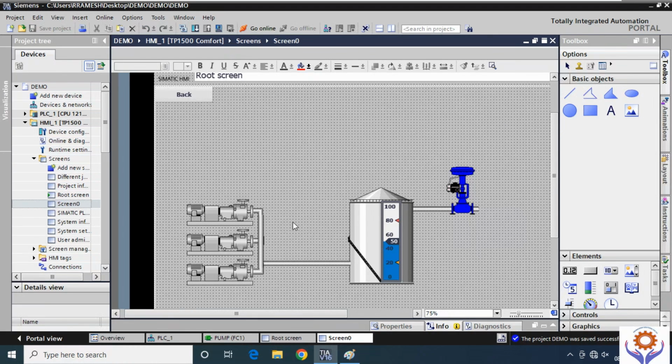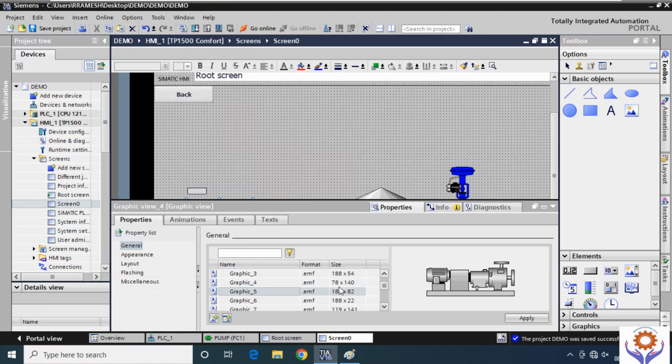I already told you for other SCADA systems also, initially you need to create the tags, but in our case, in the TIA, you already created the tags in the PLC. So we don't need to worry about creating the tags now, because now we need to link only. So for that, I am planning to make some rectangle object for the pump run signal and trip signals. I'm just taking the rectangle and adjusting it, and we are planning to give the color for that graphics.